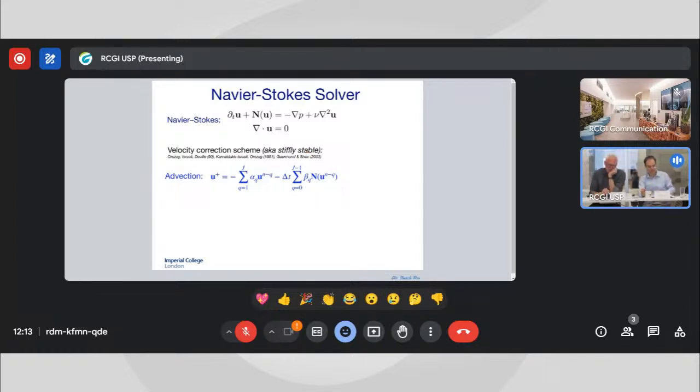So what do we do? We take our advection terms and we time march them explicitly, as we're describing. Then you have two other steps in this scheme. You have a splitting scheme. We solve independently for pressure: we take essentially the advection of the Navier-Stokes equation and get this U plus scheme here, and we feed it into a Poisson equation for pressure, the so-called pressure Poisson equation. And then this last step is an implicit discretization of the diffusion terms.